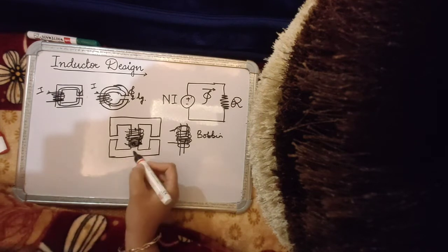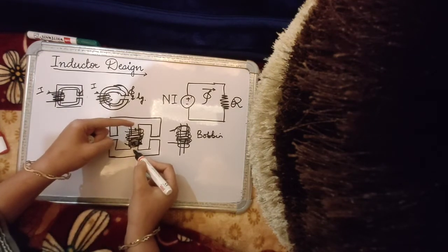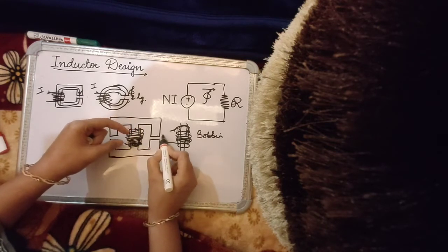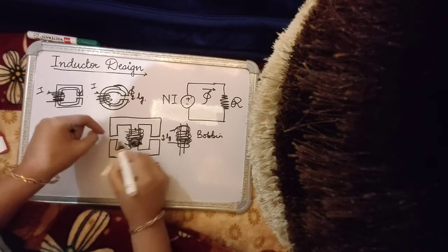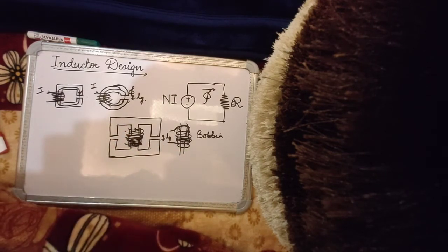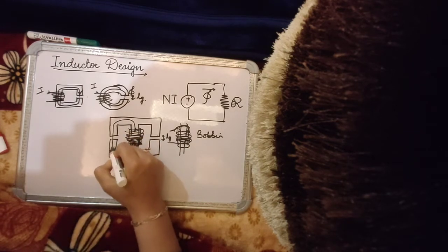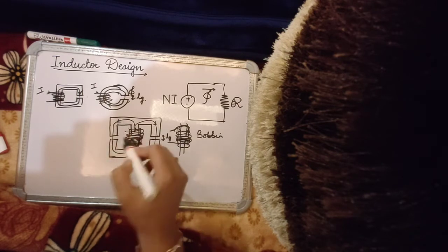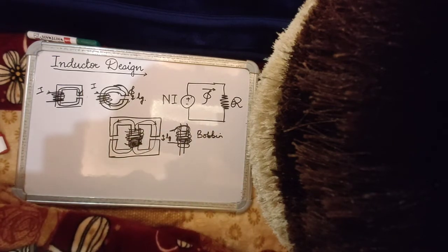And we have also discussed that how deeper you push these two E-type limbs into the bobbin, by that you will also control the length of the air gap on the left hand side and the right hand side. This is one benefit of the E-type core. The other benefit is you are also splitting the flux path, right? So within the same core material you will get more paths for magnetic flux. And your entire goal again is to minimize the area of your core, get the maximum possible inductance within the smallest possible area, or maximum storage of energy in the form of magnetic field, again with the smallest possible area. That's why you do it by restricting the path of flux within the core, within a high permeability, low reluctance path.